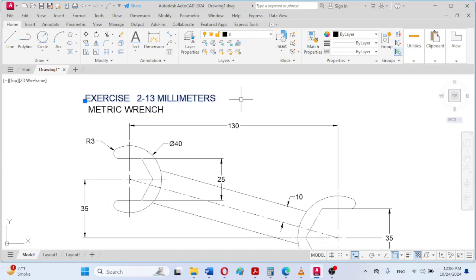And remember, if we want to change the size, we can type the scale command on the command line, and then select this object, specify any base point, and change the size like this, for example.